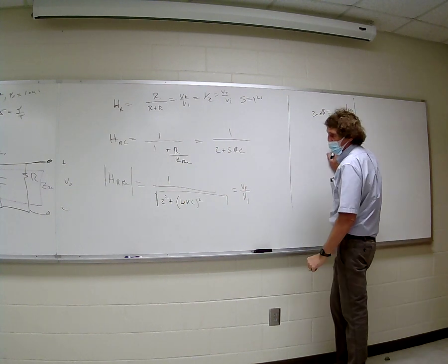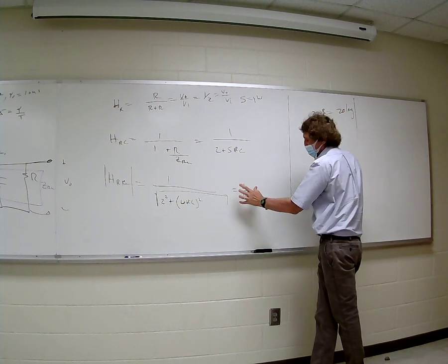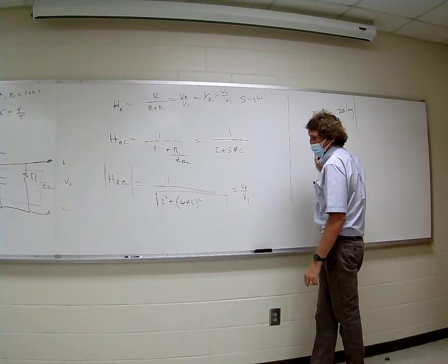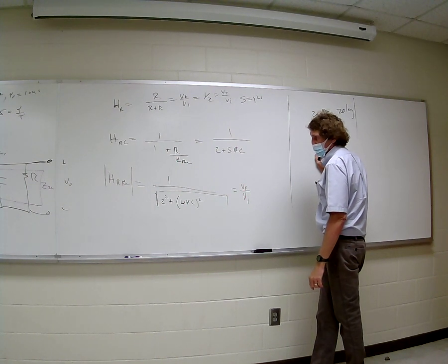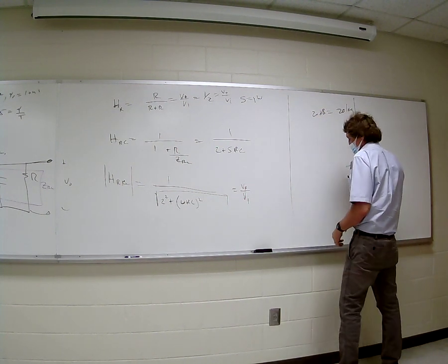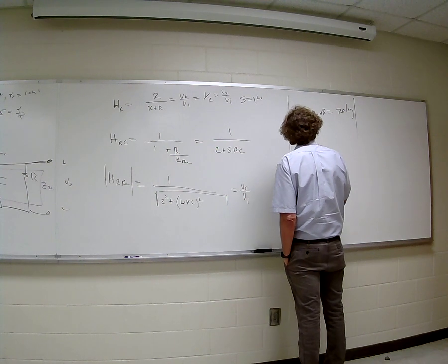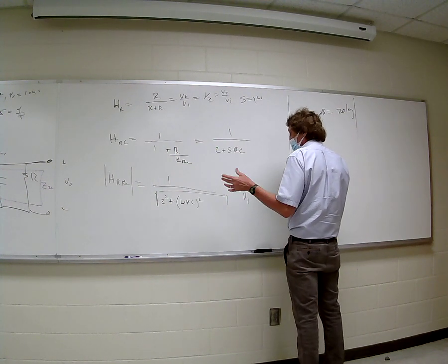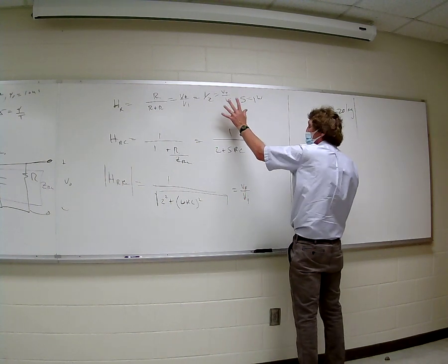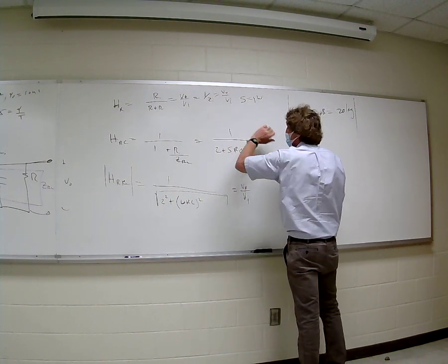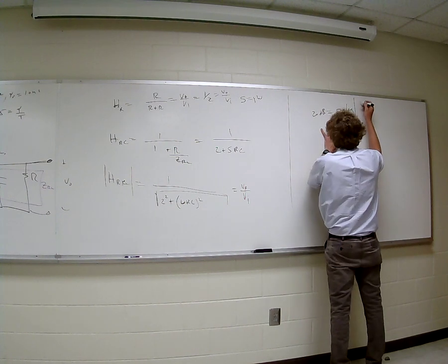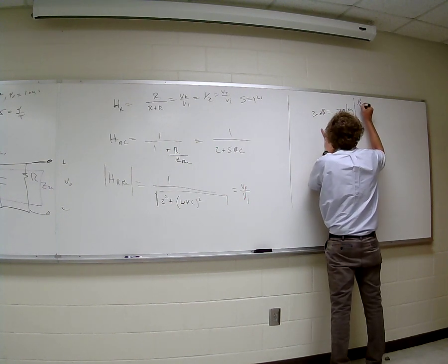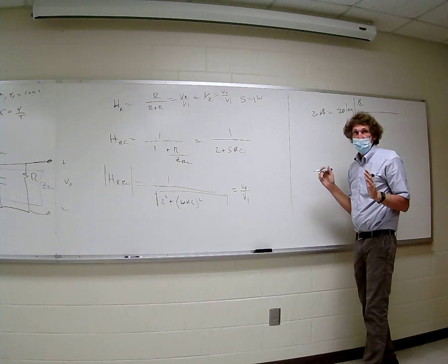So now you take the magnitude of this guy right here, V out over Vin. Normally when you say 20 dB reduction, you take the value of the input without any filtering added. It would be this. So you take V out over Vin without filtering, which is 1/2. Isn't it, class? That's the ratio.